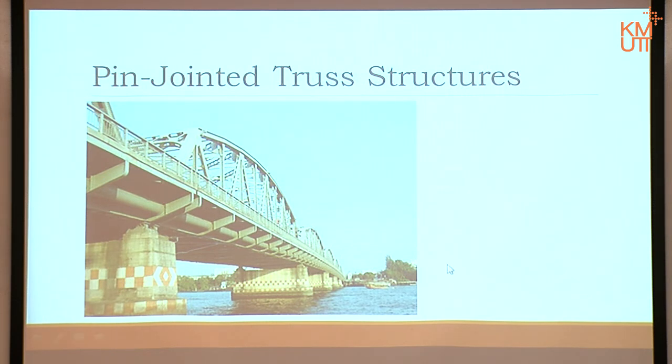Here on the top is actually the pin joint truss. The truss rests on the columns, and the floor hangs on to the structure of the truss. So the main structure of this bridge is the column and then the pin joint truss. The road, the pavement the cars run on, rests on the truss, not the truss resting on the pavement.